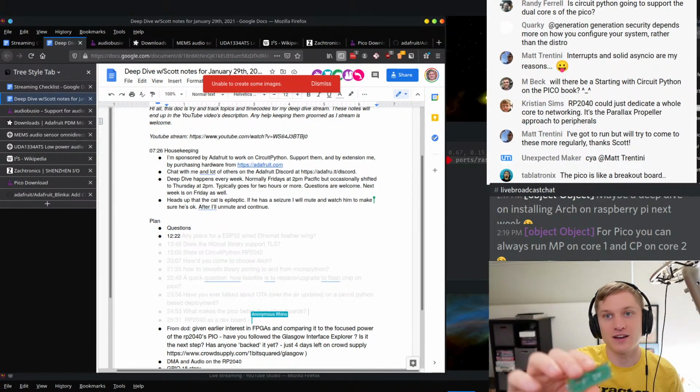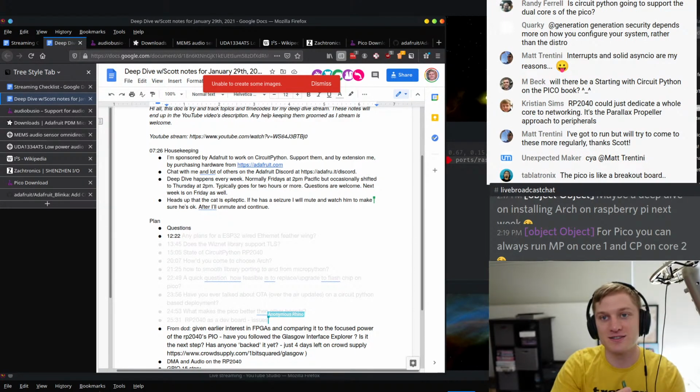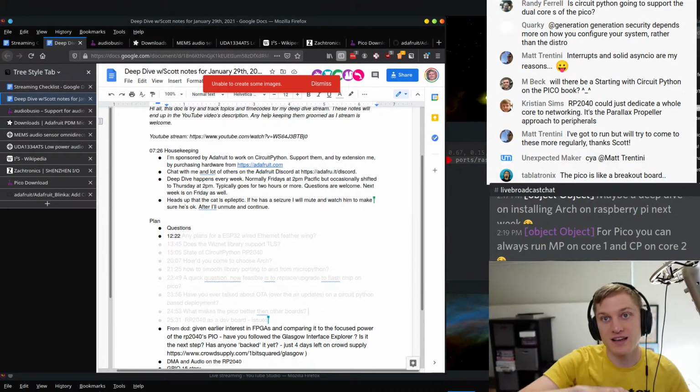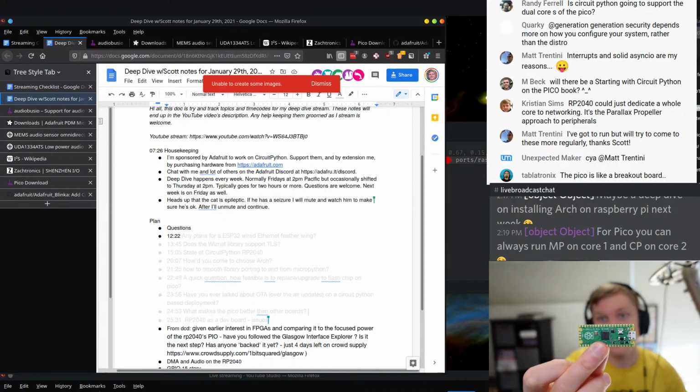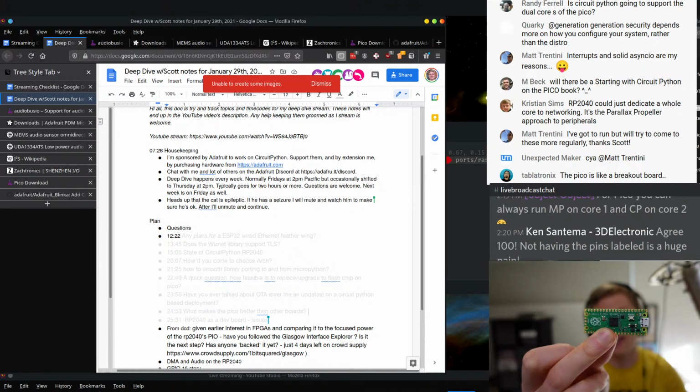Now, some people are like, oh, well, I just put this side up. But the problem is that there's a button here. And that button is the boot select button. So if you solder it down this way, you can't get access to the button. Secondly, if you want to restart the board, you have to unplug it and plug it back in because there's no reset button. So I also think that's a fail.